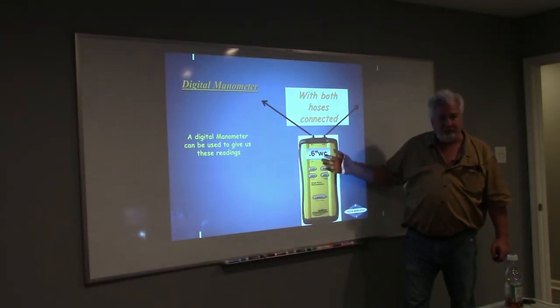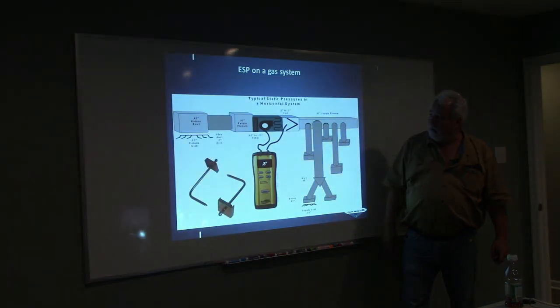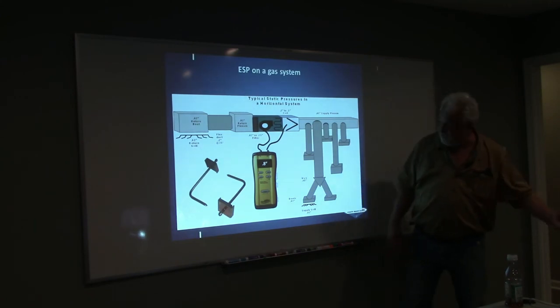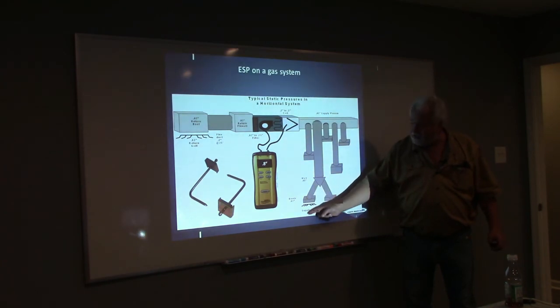Cool. Good with this? Nice. Good. Let's look. Oh my God! Look, everything has a resistance. Everything. Look at the grills. Remember that grill static that we talked about? We said we wanted it to be 0.02 to 0.03. Do you guys remember that? Look at that grill, 0.03. That's the static. That's the resistance that air has to go against.